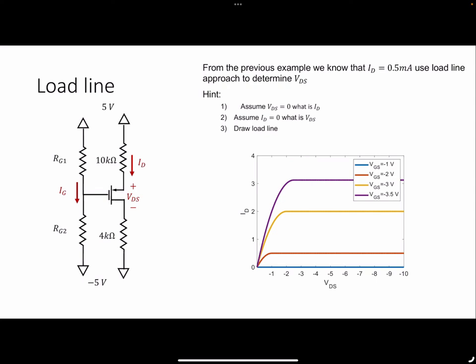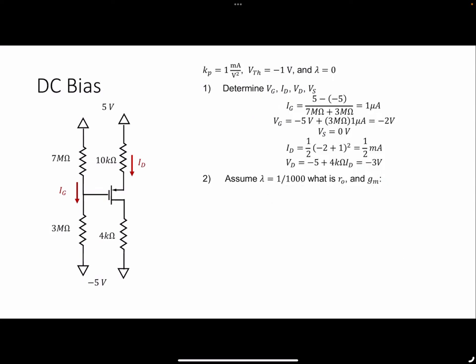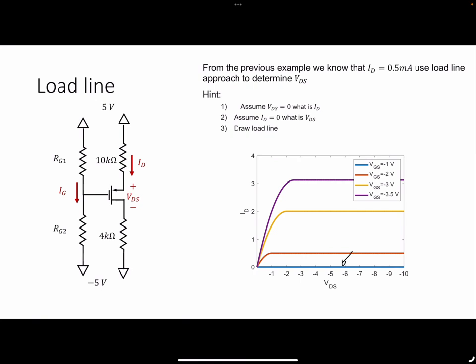Yeah, here are the lines that I was talking about earlier. Just remember that since this is a PMOS, whenever VGS minus V threshold is greater than 0, this thing is inactivated. So for any of these, you need VGS minus V threshold to be less than 0. If this was an NMOS, it would be the opposite relationship.